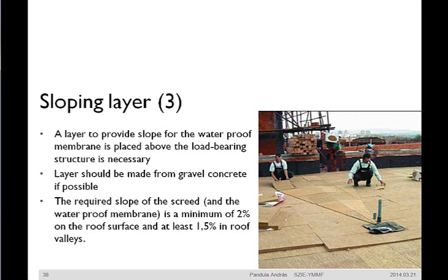Provision of the required slope for green roof is even more important than for other roof types, because damages originating from insufficient water drainage can be repaired later only with difficulties, and generally locating the place of fault is not a simple task.